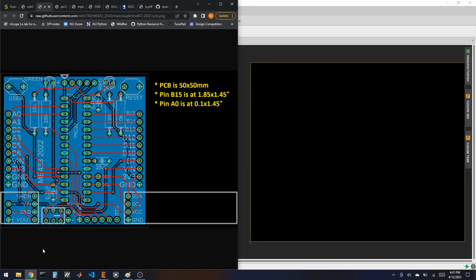So something we can take from this design though, we're going to put the PIC in the middle because the PIC is kind of the heart and it has a lot of connections that fan out from either side. Things that we need to touch or see should go at the edges, because if there's a board on top of this board, we won't have access to them later. So we'll put our buttons towards the sides and the LEDs.